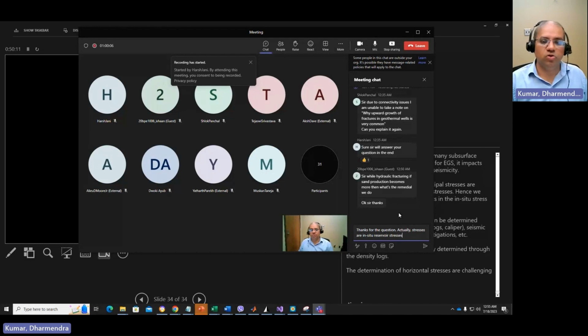But at the same time, if you remember, I've shown one example when we use very small proppant size. So even with the small opening of this natural fracture, proppant can still go to those natural fractures also. But in practice, even in field practice, it's not very much known if you have natural fracture reservoir where the proppant is going. Mainly, it's staying in the hydraulic fracture because that's where it gets more opening and more pressure gradient.